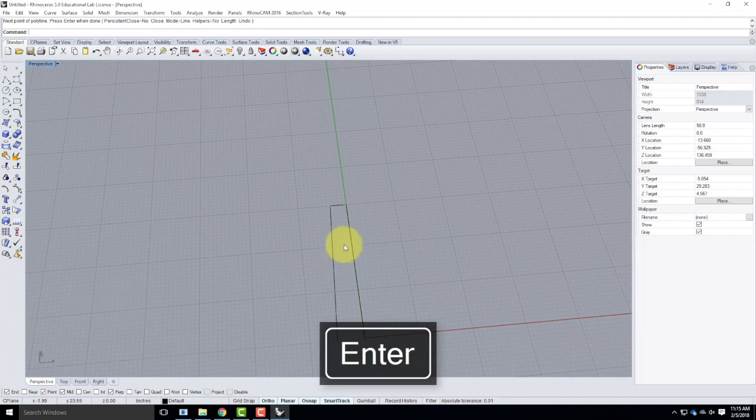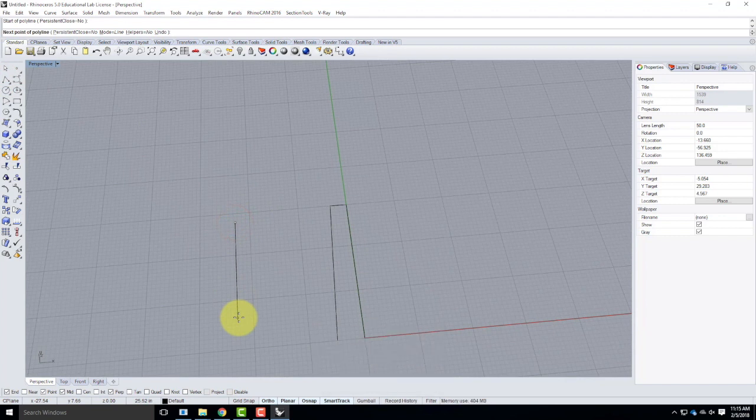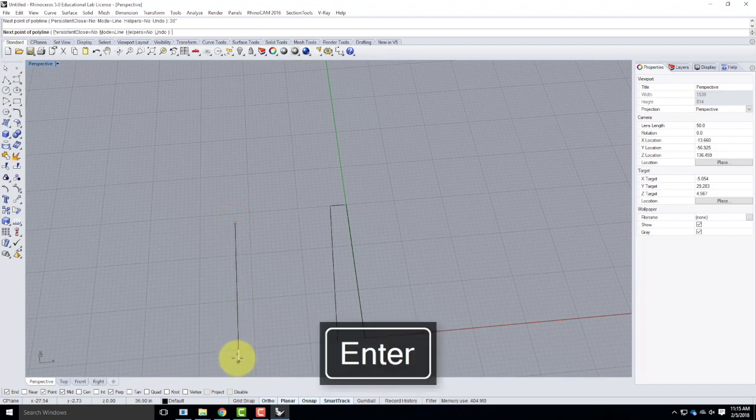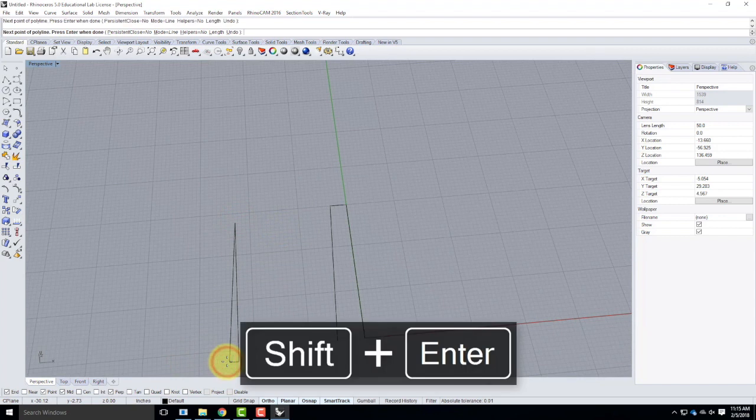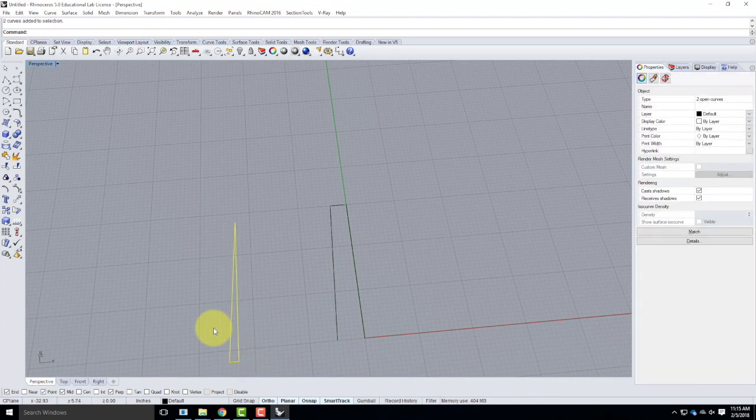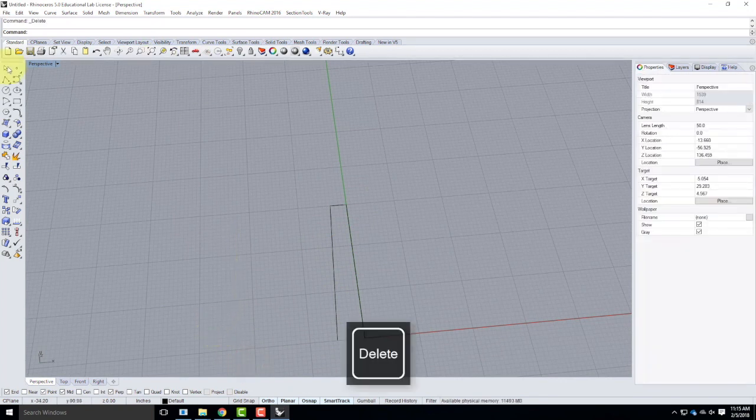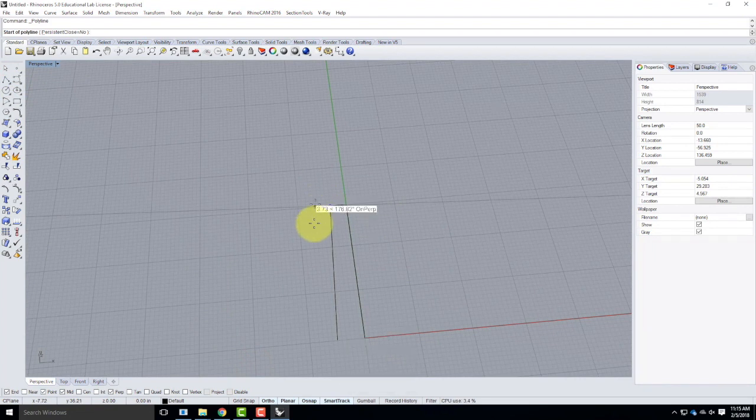If I didn't do it that way, I'd be stuck saying, oh, well, let me create a guide that's 36 inches, and there it is, and let me go over 2 more inches. Okay, there it is, and then let me create another piece that goes from here to here, and then I could join that in with everything else. So it's a lot of extra drawing that's really unnecessary. So if you get used to the idea that that coordinate system can be beneficial, you could just say at -2, comma, -36 and get there.